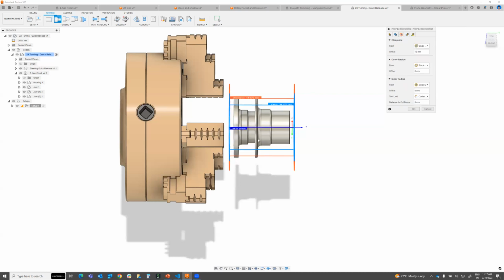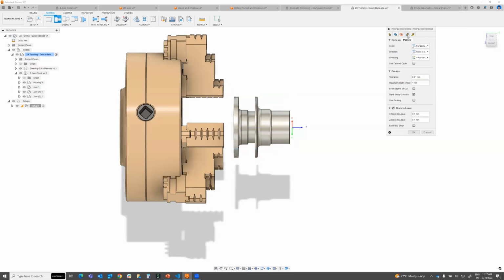Then after that, for the safe clearance, it is possible to set the safe clearance here, then the number of passes, like whether you want to do horizontal turning or vertical passes. The vertical will do passes in this direction, horizontal will do passes in this direction. Then you can choose whether you want to avoid the grooves, or cover the grooves wherever possible. You can allow the axial groove or the radial groove, or not allow them. If you want to allow both, just select this, and if you don't want to allow, then it will not do any grooves whenever they come inside the profile.